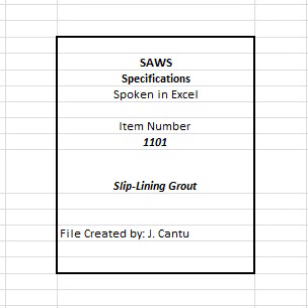3. Mix designs: one or more mixes shall be developed to completely fill the annular space based upon, but not restricted to, the following requirements. A. Size of annular void. B. Void size of the surrounding soil. C. Absence or presence of groundwater. D. Sufficient strength and durability to prevent movement of the liner pipe. E. Provide adequate retardation. F. Provide less than 1% shrinkage by volume.